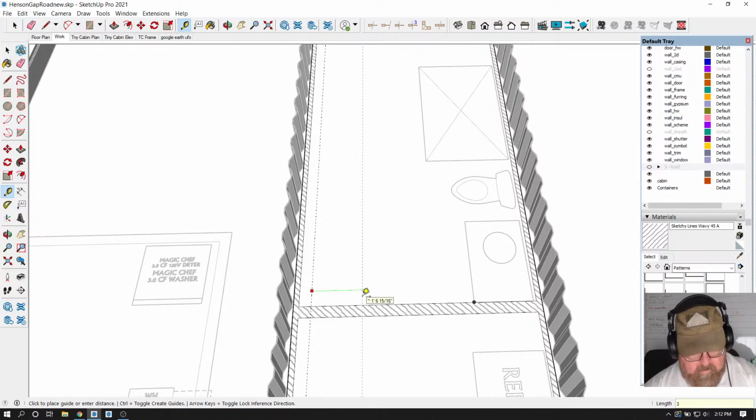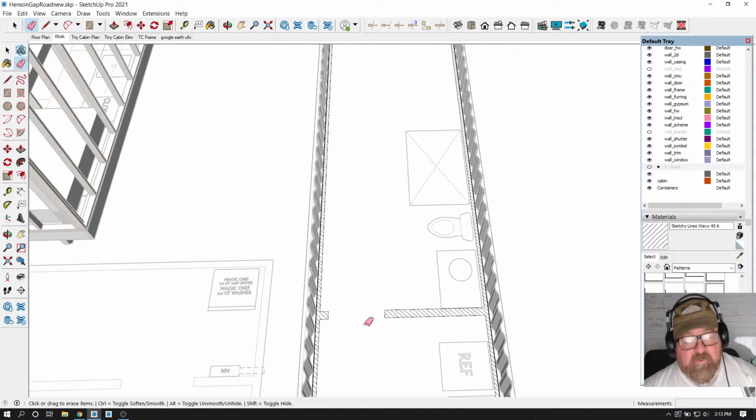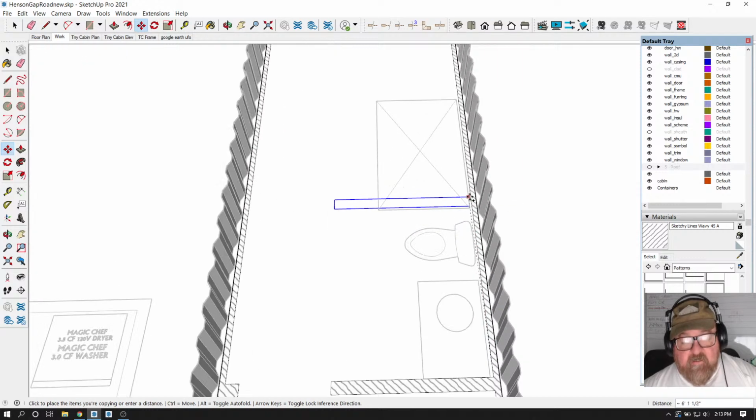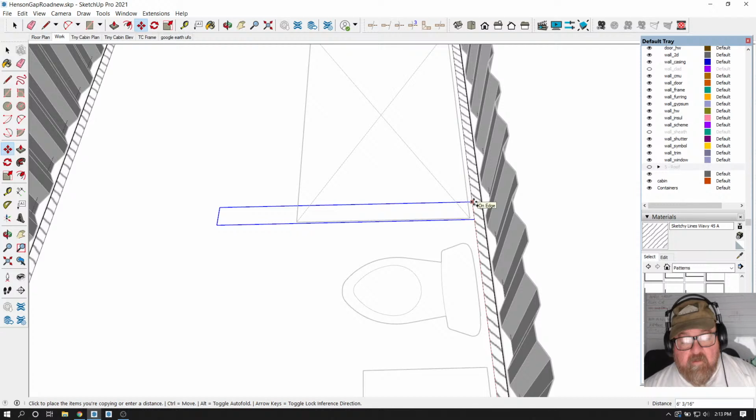You need at least a 30-inch door here. That's what we normally put in bathrooms. You can get by with a 24-inch door, but I'm going to show that. And then I'm going to go ahead and show, see here, I'm doing exactly what I didn't want to do. See, that's a little too close. It would have to be at least right there.